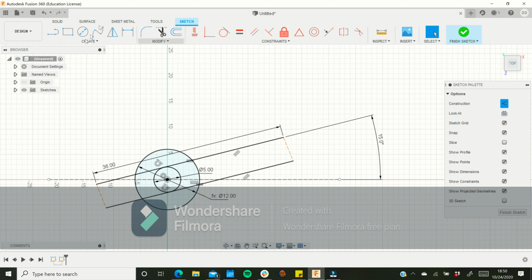And now I'm going to dimension the angle between here and here. Let's say I want it to be 85 degrees. No, let's make it 80 degrees. I want a parallelogram. Now these 2 points here are fixed in space. Now all I have to do is, because I can still do something, can't I? Yeah, I can still drag it back and forth this way.